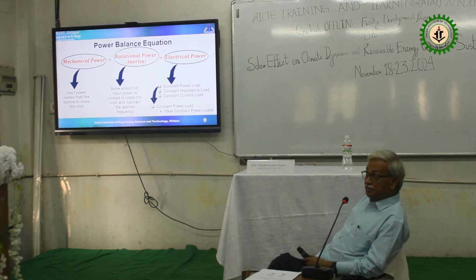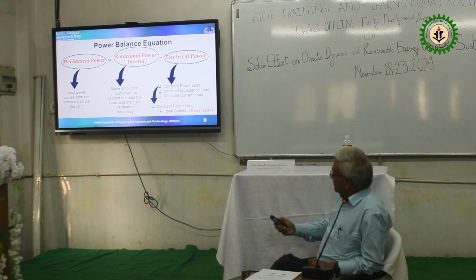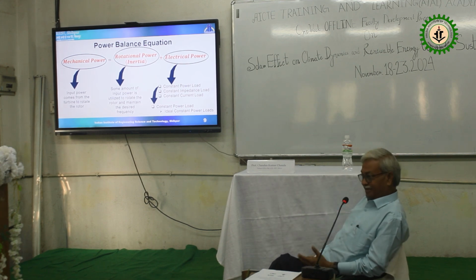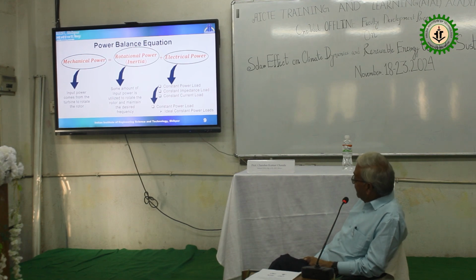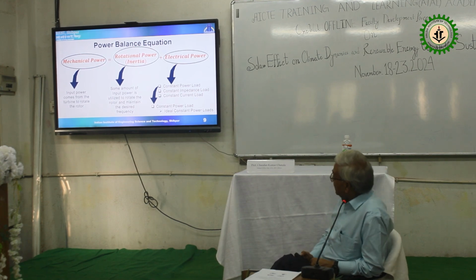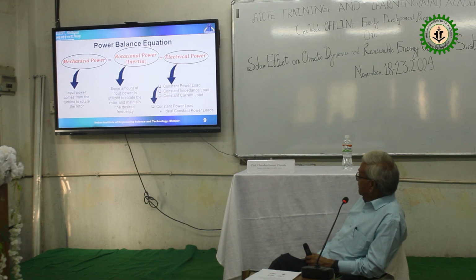So it seems 20 units of energy are wasted. But it is not wasted; it is there in the form of kinetic energy and inertia. So the input power comes from the turbine, and some amount of input power is utilized to rotate the rotor and maintain the desired frequency.